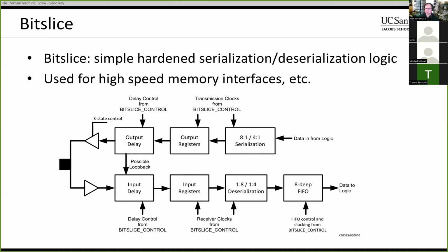As far as I can tell, it's implemented with the exact same silicon. It's basically the IOB logic that implements this. You can set it in two different modes. One of them is a native mode, the other one is a component mode. I don't know exactly what the limitations are of the component mode. It does seem like the bit slice can run faster, but they can both do 1.25 gigabits per second. So it might be necessary to investigate both of these and see what's possible.